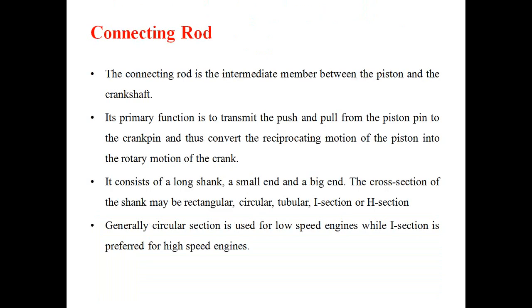What is a connecting rod? The connecting rod is an intermediate member between the piston and the crankshaft. The primary function of the connecting rod is to transmit the push or pull from the piston pin to the crank pin and convert the translatory or reciprocating motion of the piston into rotary motion of the crank.